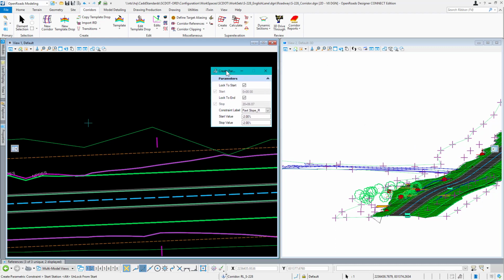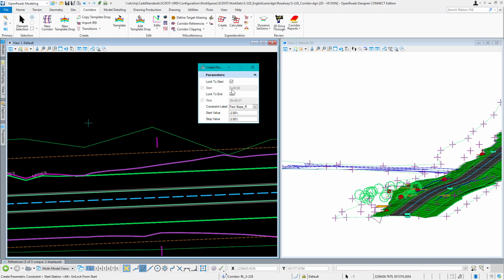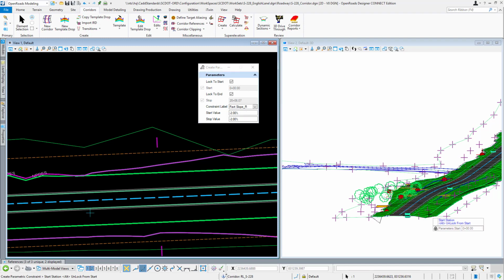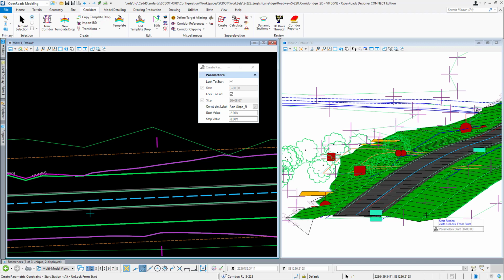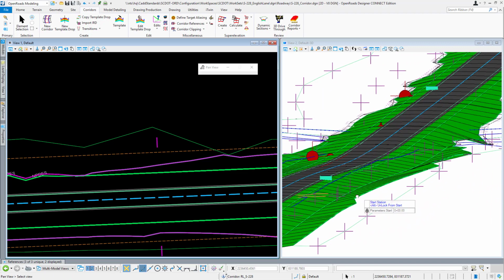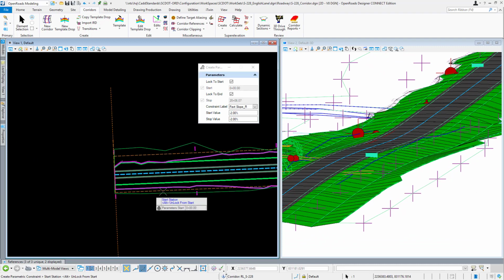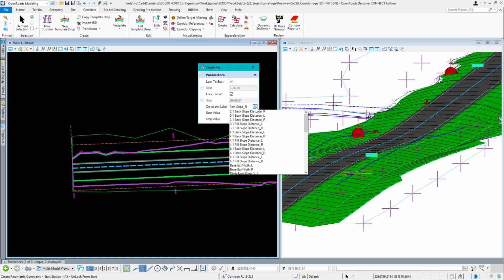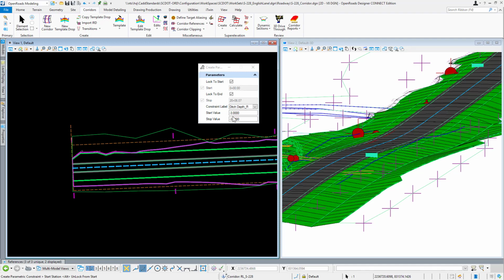And here we can see our toolbox. We have start, stop, and we have some other options like values and the actual constraint we want to do. So before I enter anything, let's choose something. I want this ditch depth on this right side to run more shallow than 3 feet. We don't want to cut over into there right away too much. So let's see what it is right now. We'll go to the drop down and go to ditch depth right. So it's set to -3.